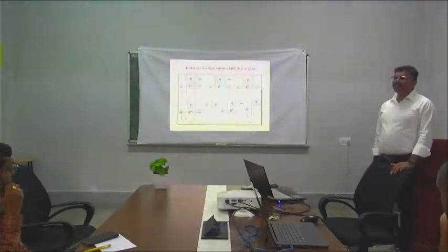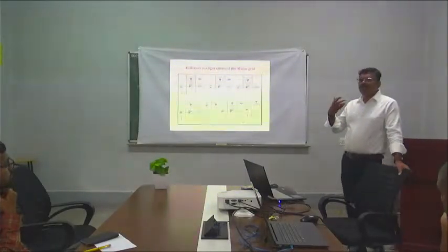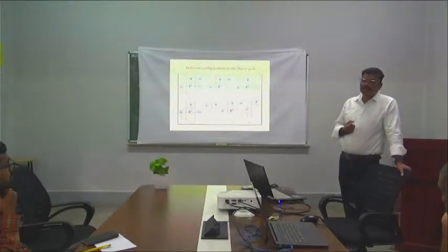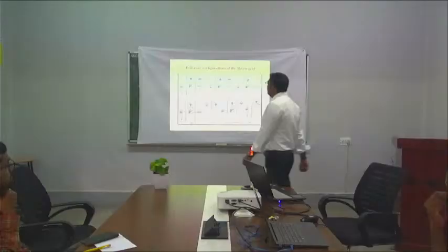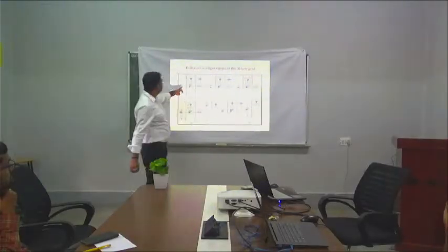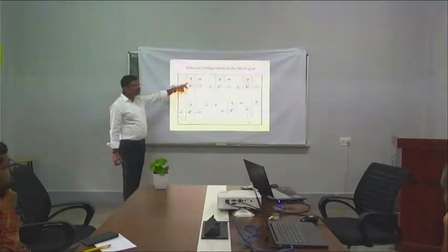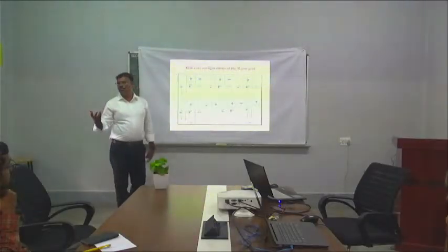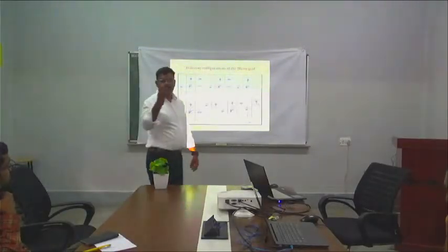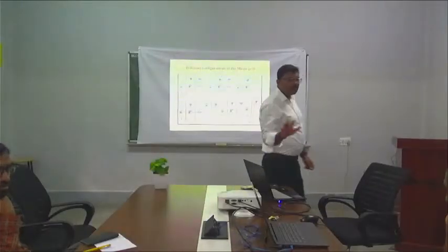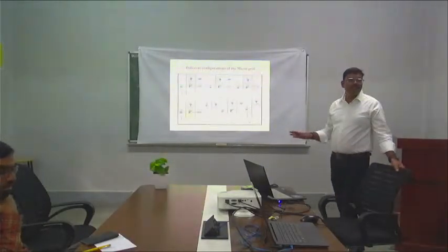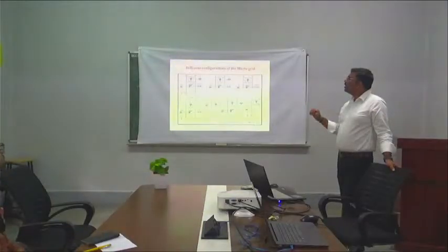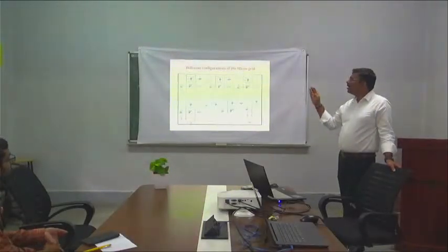Now, when you enter into the Homer software, you have different types of DGs there. This is the representation of the Homer symbols. You have the primary load, you have biomass, you have wind. There are other sources also that I have not taken. As he told, fuel cell is also there, but I have not considered it for my simulation. Fuel cell is not considered. I considered only biomass, wind, solar and DG.